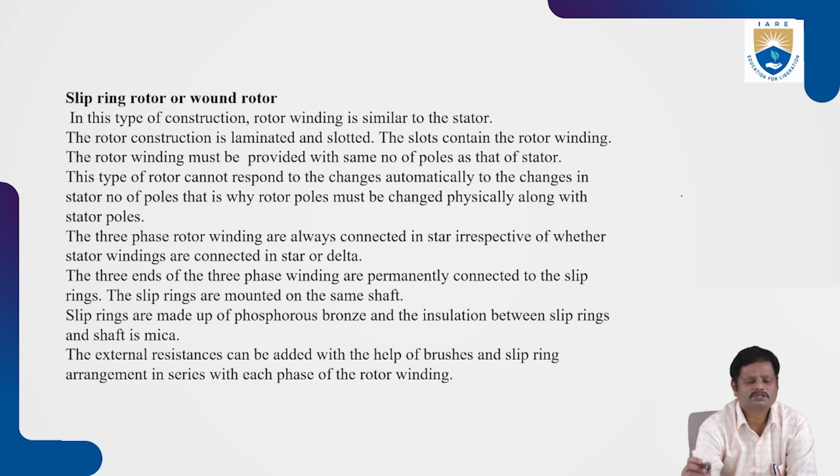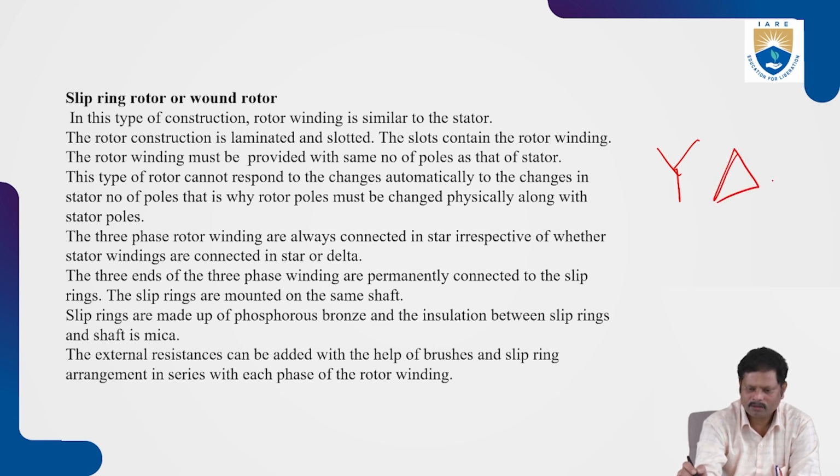The three-phase rotor windings are always connected in star instead of delta, and coming to the stator windings, they are connected in star or delta.